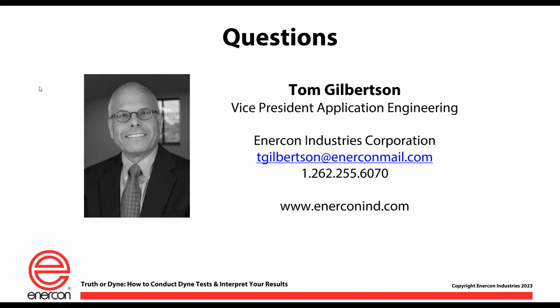And further to that, if you decide to go that way, pick a vendor who is measuring the surface tension of the fluid. So here's what I'm saying to you guys. If you're buying a bottle of 38 Dyne fluid, make sure you go back to the supplier and ask, do you have a test method?